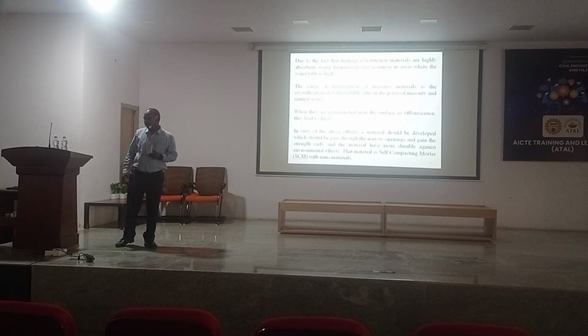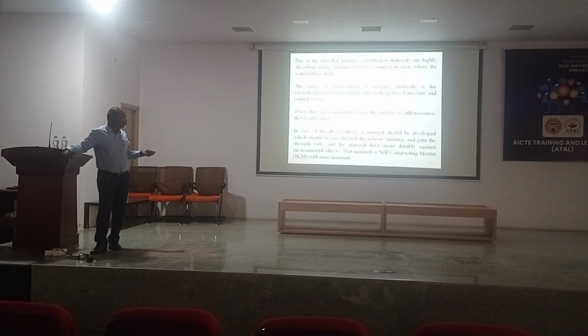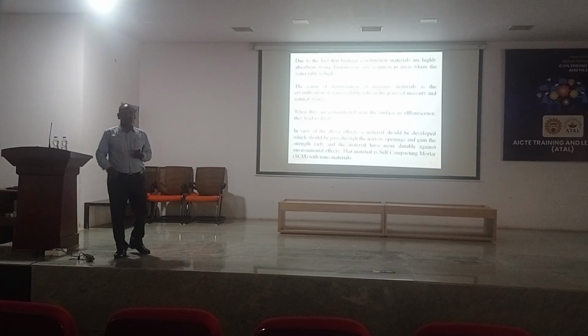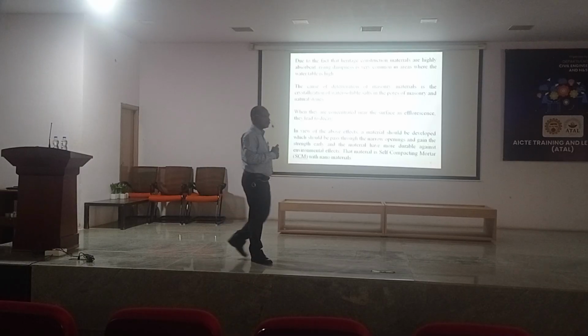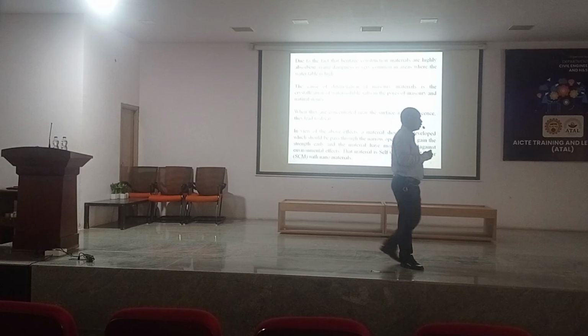Okay, in view of all these issues, the best material is self-compacting mortar as a repair material. In view of the above effects, the material should be developed so that it can pass through narrow openings, as already explained in the beginning, and gain strength early. That is one of the advantages. And the material has more durable strength. So these are the advantages of self-compacting mortars. It can easily pass through narrow openings, settle fast, gain strength fast, and it should be more durable.